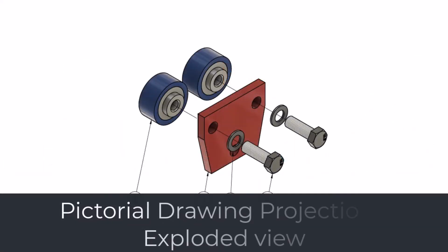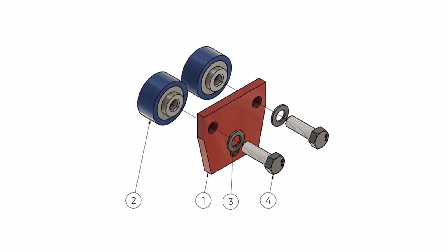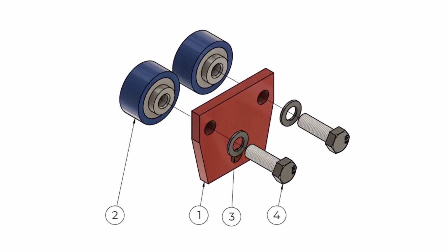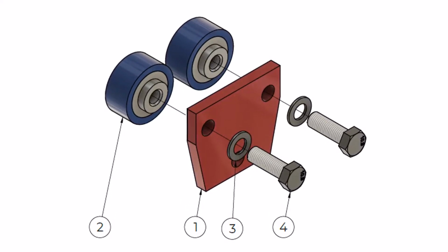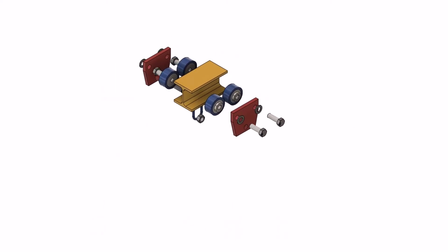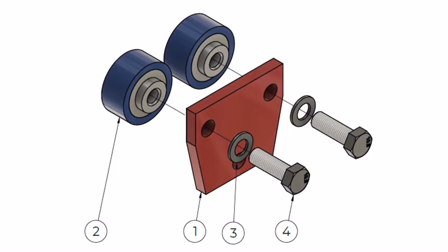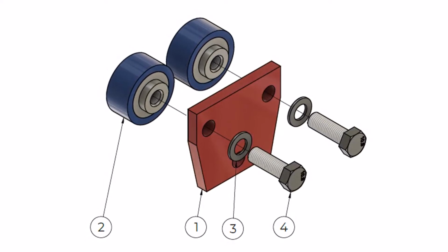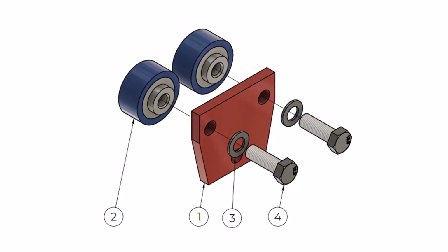Exploded view. The exploded view illustrates the relationships between different components that form an assembly. In other words, the exploded view shows how various components are put together to form the assembly. The exploded view shows the assembly disassembled rather than showing the part completely assembled. This type of view is usually used in parts catalogs, user manuals, work instructions, assembly instructions, etc. The assembly components in exploded view are shown in the same axonometric projection, usually isometric projection. Therefore, the most important aspect of creating the exploded view is to choose the view direction that shows as many components as possible.